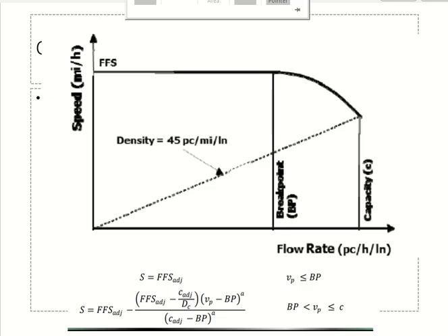We cannot say it's because upward I have more cars. We don't have more cars, right? The volume is same. So what made the upward higher? Slower. The heavy vehicles, right? The effect of heavy vehicles increased for upward condition. And that effect is shown in the flow rate itself. That's why this is a very good metric to include here.